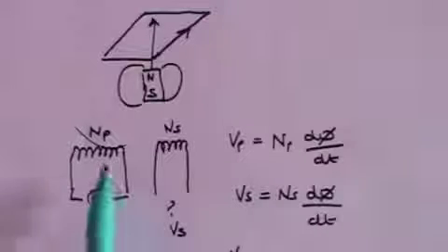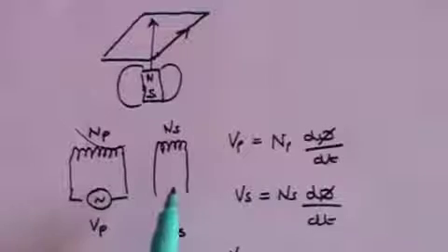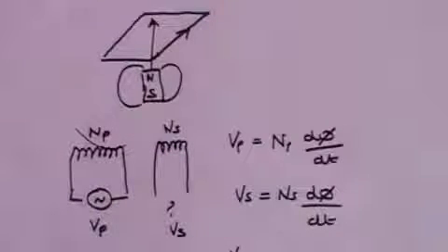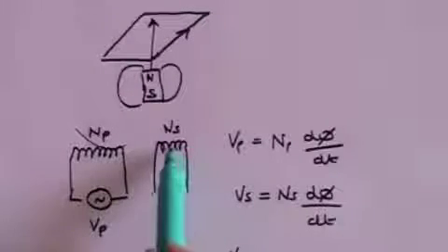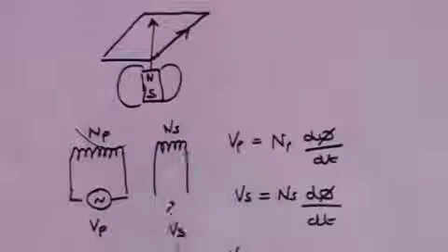So you can either step up or step down the voltage, and we explained this in the video, depending on how many turns you have. If you have fewer turns, then you get a smaller voltage. If you have more turns than the primary, you get a higher voltage. So you can step up or step down as the case may be.